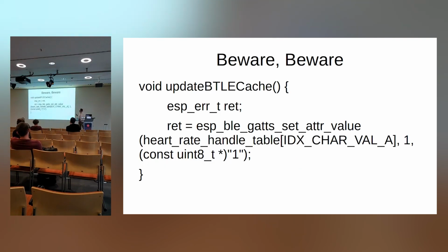And there is another trap, a big trap. This table, which contains the representation objects for the individual mailboxes, gets updated only very, very late in the Bluetooth stack's life cycle. And if you invoke it like this, if it's uninitialized, what happens? Wrong. Nothing happens. It doesn't even throw a warning into the monitor. Nothing happens. This is another big trap to keep in mind, this table.